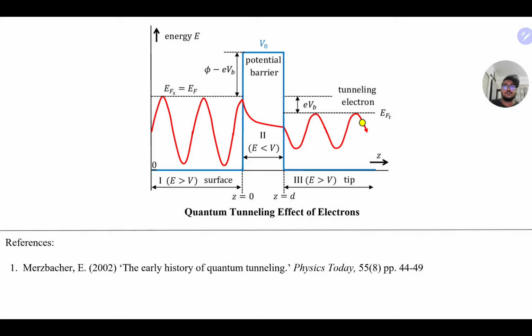T-FETs generate current through the use of quantum tunneling effect. Quantum tunneling is the phenomenon where an electron can pass through a potential barrier even though they're at a lower energy state. Now, if we see the construction of a T-FET and compare that to the traditional MOSFET, it will all make sense.